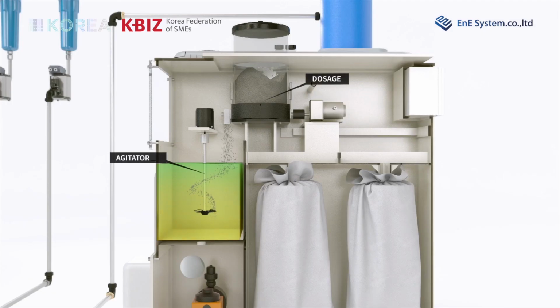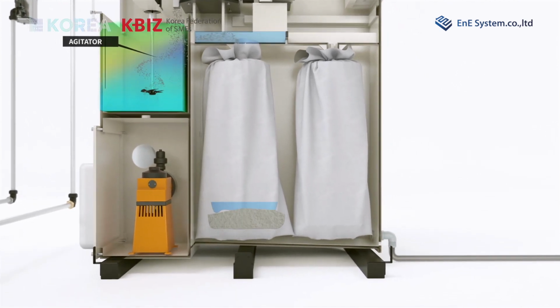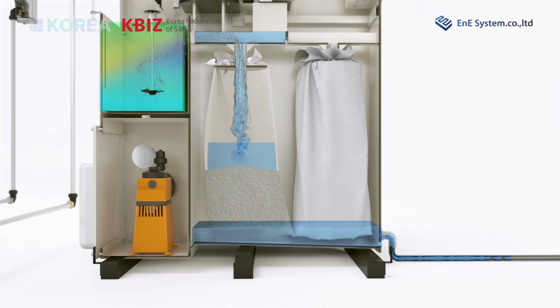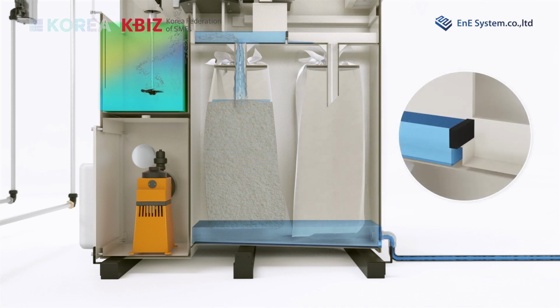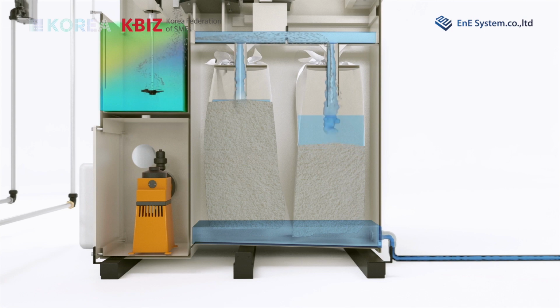Here, it is mixed with chemicals by the agitator. Separation and decomposition of emulsion takes place at the same time, and flocculation, flock in the form of wool, occurs within the agitator. The flock is collected and filtered out by a filter bag so that only clean water is discharged safely through a lower drain line.